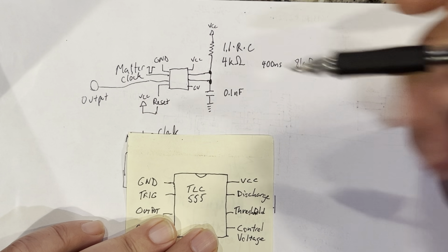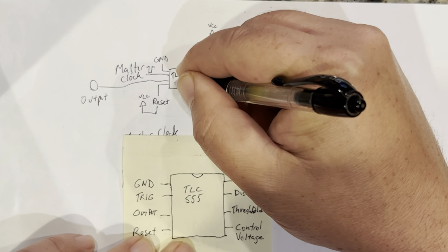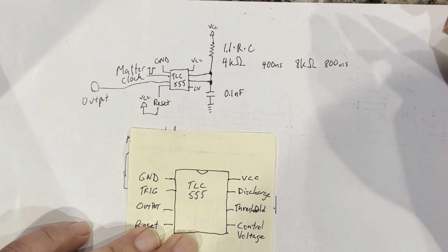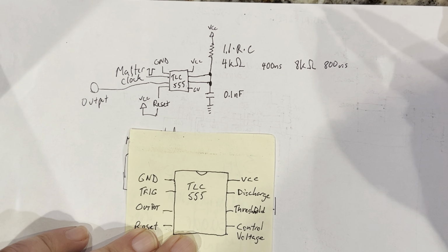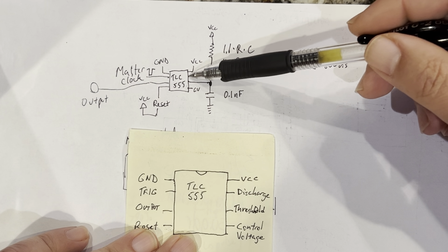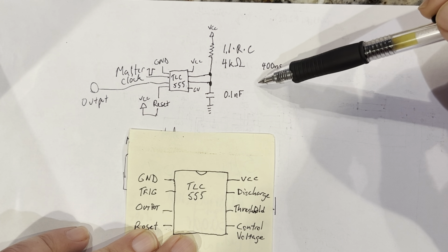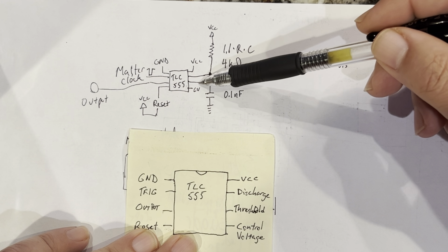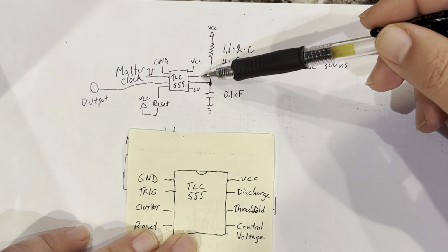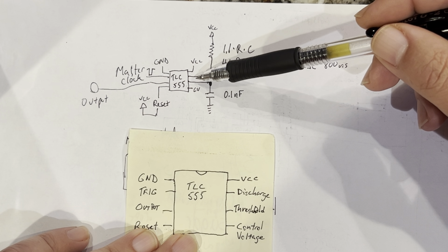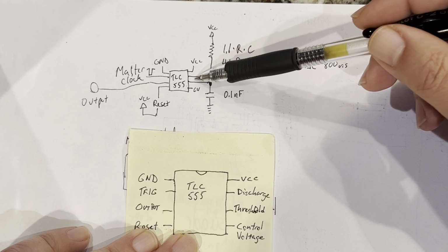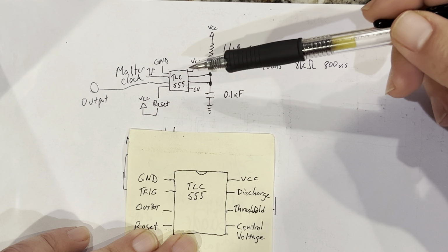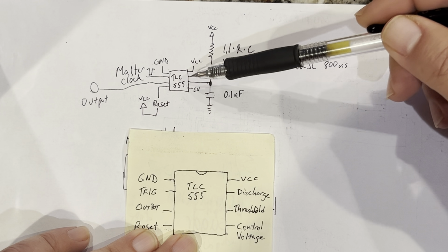And then when I looked at the data sheet of the TLC555 timer, in the fine print in the monostable mode, it was mentioned that the comparator inside this that does the triggering is a little slow, and it can have a delay of up to 1 microsecond to turn on and off, and therein lay the problem.